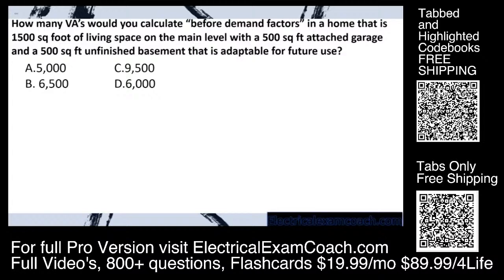How many VAs would you calculate before demand factors in a home that is 1,500 square foot of living space on the main level with a 500 square foot attached garage and a 500 square foot unfinished basement that is adaptable for future use?